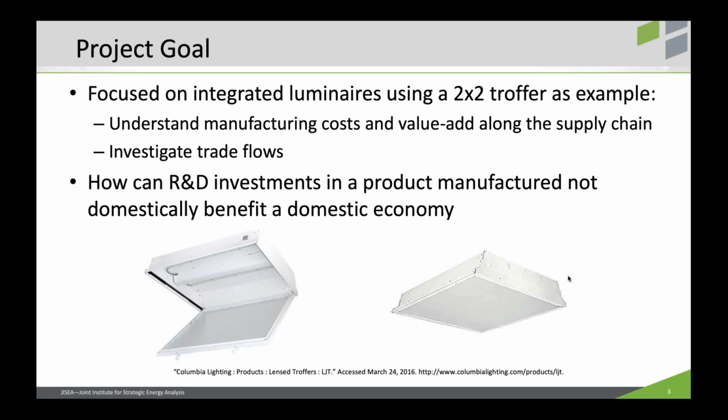For those of you who don't know what a luminaire is, you're in good company. When I first started, I was like, what's the luminaire? It's basically the entire fixture with the light generating device. In previous technologies, the fixture would come and then you'd buy your bulbs and put them in. But now with solid state lighting, you have these LEDs integrated within the light. There is no thought that you're going to change out something later on or the bulb will burn out. An integrated luminaire has the LEDs built into it. It has the drivers or the necessary power electronics, and then it has the frame and the light diffuser and all those pieces. For the project, we used a 2x2 troffer as an example.